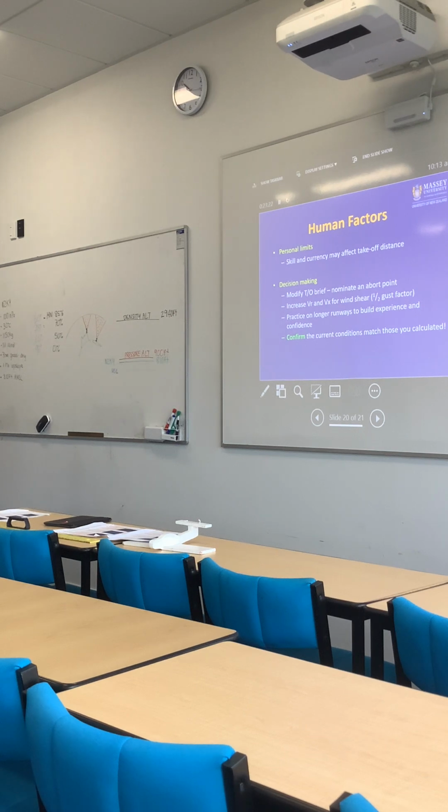Before you take off, remember we've calculated all of this inside perhaps an hour or an hour and a half before we actually go to get airborne. We need to check that the conditions we're using are still valid. So what I tend to do in the performance briefing is check the temperature, check the QNH, check the wind. Make sure it's still valid or hasn't turned in an unfavourable direction. For example, hotter temperatures, lower QNH, less wind. Those things invalidate your calculation and might mean you actually need more runway than is available now. So we might decide not to go. Again, that is really important.